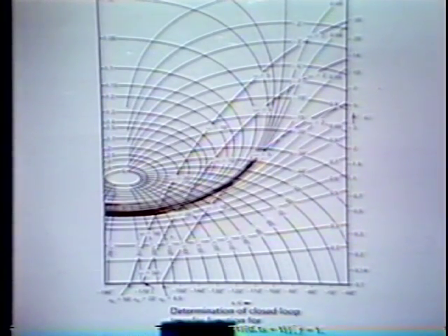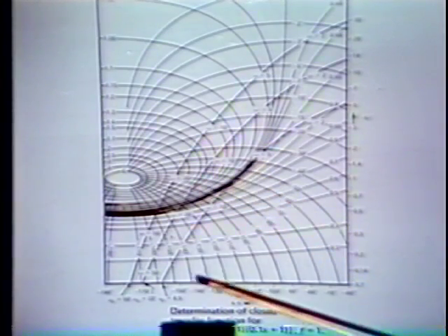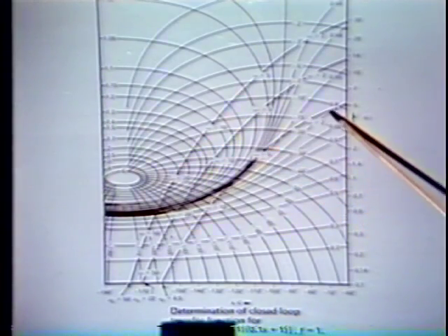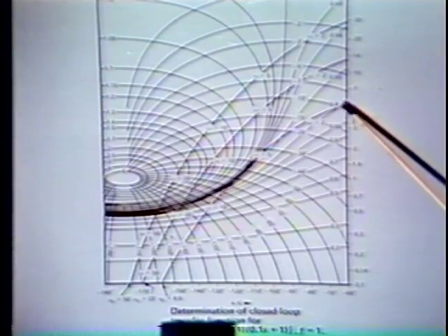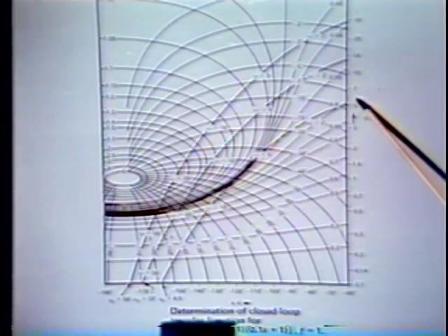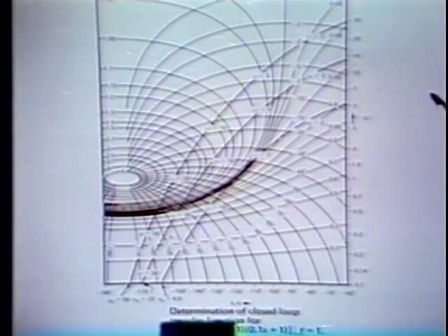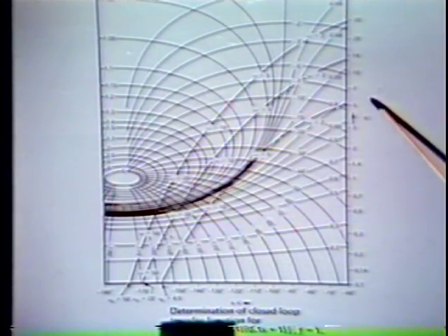And what we're able to do then is determine the closed loop gain of our system by simply going ahead and looking at the magnitude of G over 1 plus G in these coordinates, and if we cared to, the angle for various values of omega and a specific value of A0. And we can see how that works. For example, if we look at the AF product that corresponds to an A0 of 8.5, we find out that at sufficiently low frequencies, back near omega equals 0, this curve eventually levels out at 0 degrees and a closed loop magnitude of about 0.9. We can get that either by analytic manipulations or look at the complete chart. We find out that the low frequency closed loop magnitude for this system with A naught equal to 8.5 would be about 0.9.